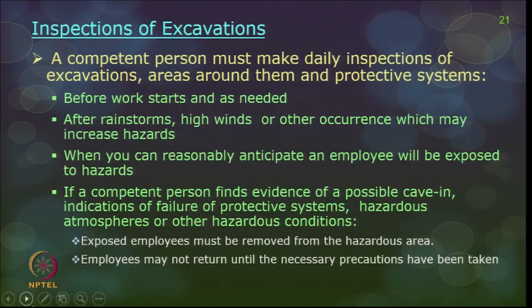Now, you have to do inspections of excavations as the excavation work is going on. So, a competent person or a site engineer or site supervisor has to make daily or periodic inspections of the work. Under certain circumstances he also has to do this inspection regularly before the excavation starts, and as and when needed, maybe after a heavy rainfall or after an incident or an accident, you have to be really checking on the site conditions. After rainstorms, high winds or other occurrences, you may have to do the inspection.